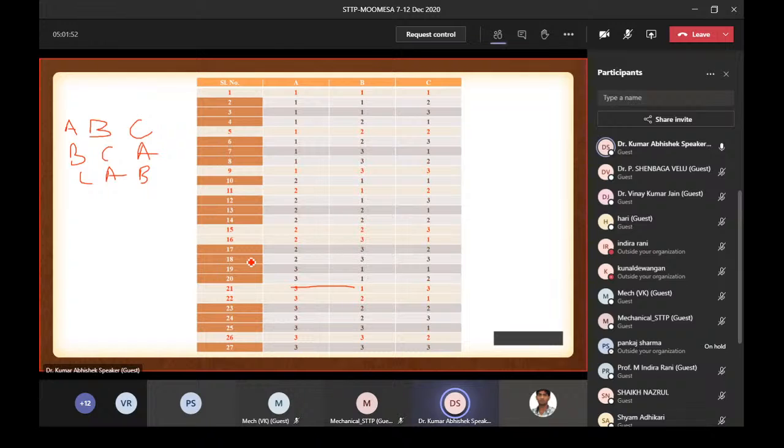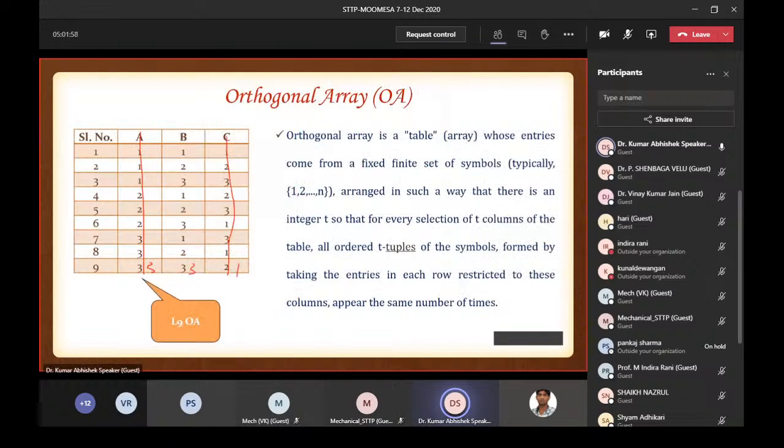Even if you haven't done the experiment, you can also perform its result in order to validate your result. So far you have seen how Taguchi is going to reduce the number of experiments. Taguchi reduces them by using the orthogonal array concept. The orthogonal array concept is based on the format of a lattice matrix. That's why the experimental design in Taguchi has been represented with the letter L. Am I clear?